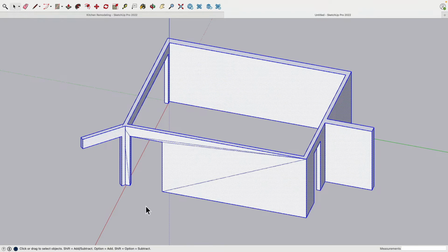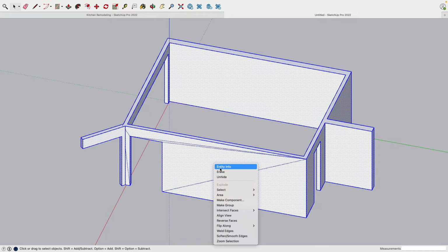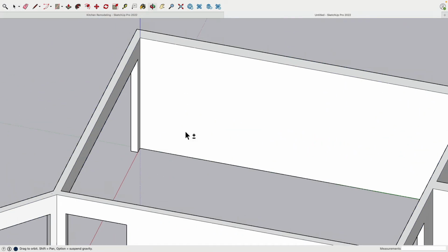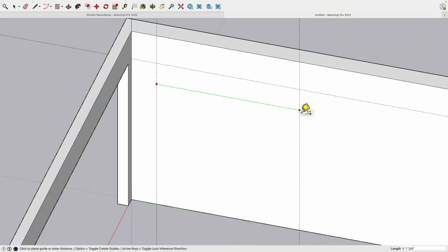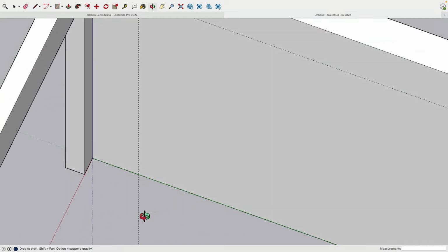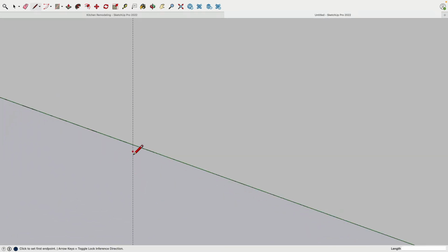This whole wall has to be grouped. So let's make a group. There we are. Now, I know from the top down 15.5 inches, and here from this corner 1 foot. Very nice. Okay. And then 97.5 inches to the right. This is not the opening, but this is where the trim actually would sit on. So let's actually create the trim. I go more in a top view. Here I start trying to figure out where this intersection is. There it is.